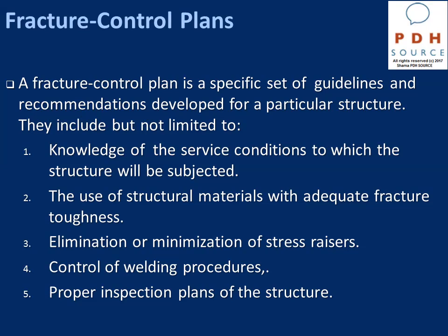Control of welding procedures is very significant, because most of the fatigue cracks are localized in the welding area due to poor welding procedures.